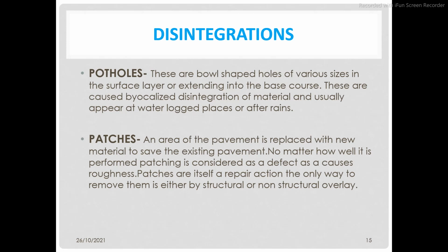Potholes. These are bowl-shaped holes of various sizes in the surface layer or extending into the base course. These are caused by localized disintegration of material and usually occur at waterlogged places or after rains.